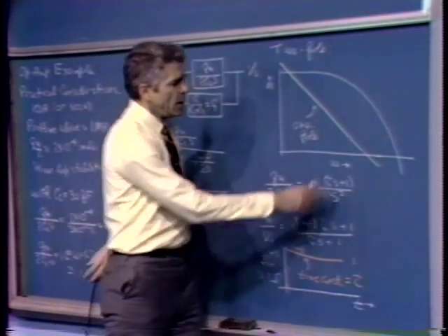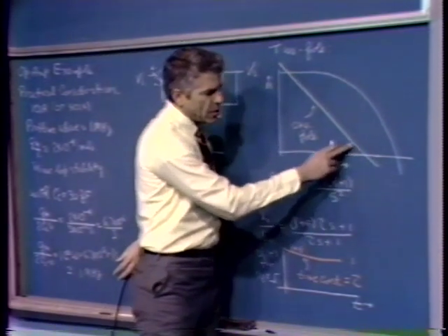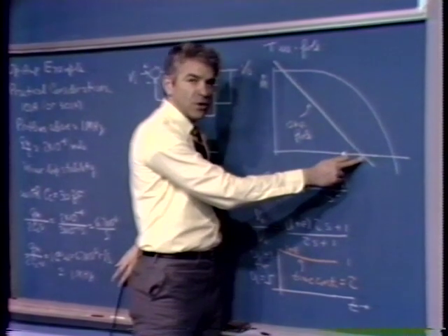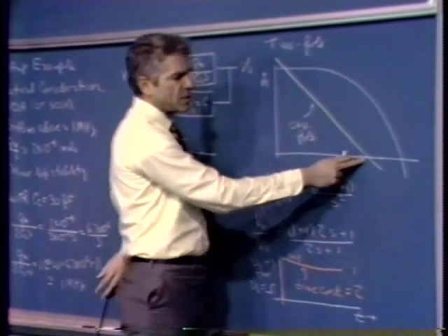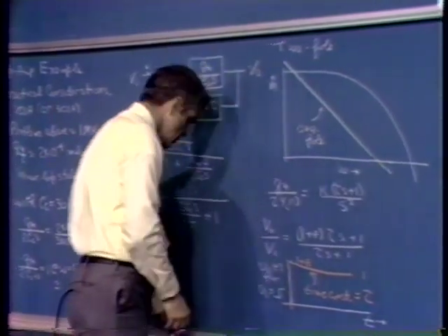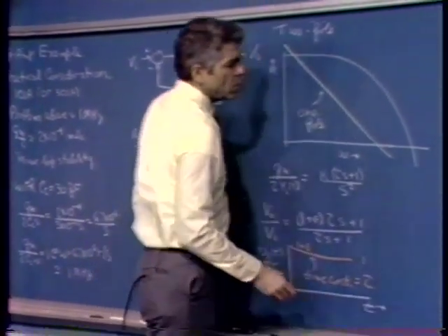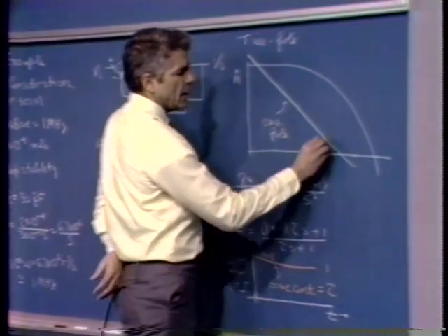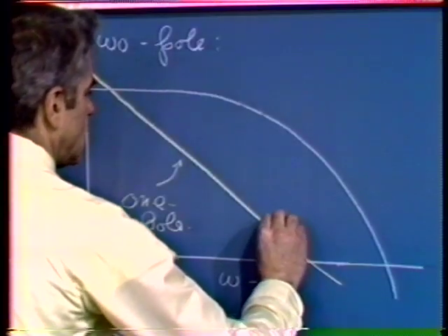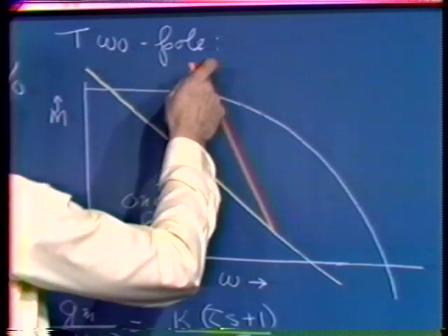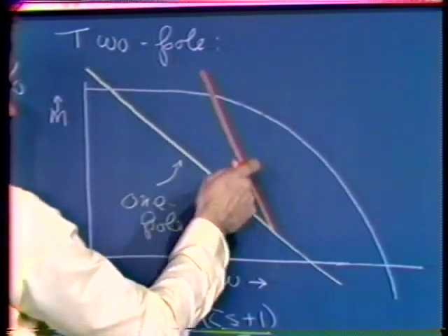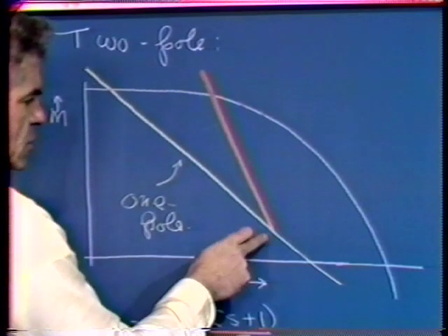Well, what would happen if we used a somewhat different kind of roll-off, a somewhat more heroic roll-off, if you will? Let's keep a single pole roll-off in the vicinity of crossover. Let's assume this is a plot of the AF product, so it includes F. Let's keep a single pole roll-off in the vicinity of crossover, but let's roll off as 1 over s squared at lower frequencies. Maybe something like so.